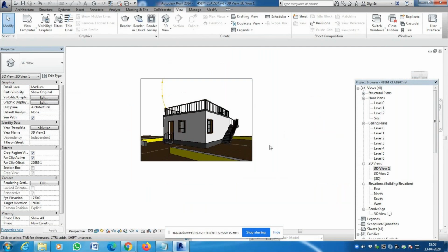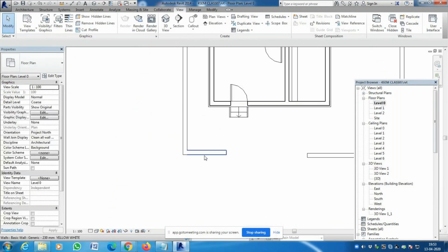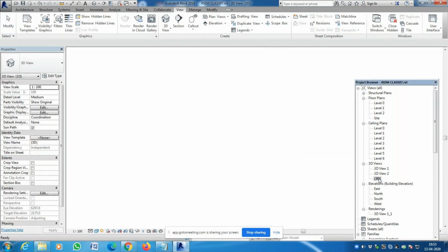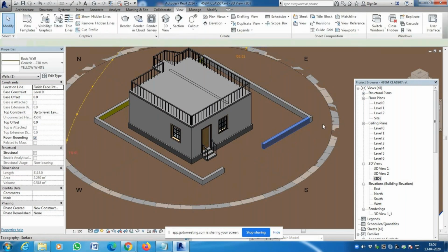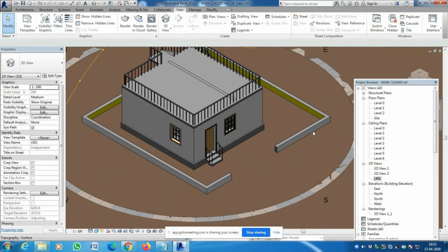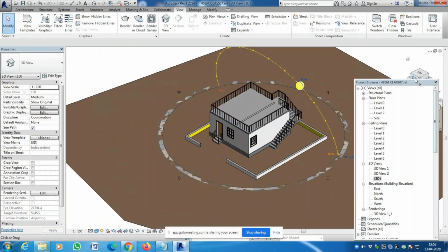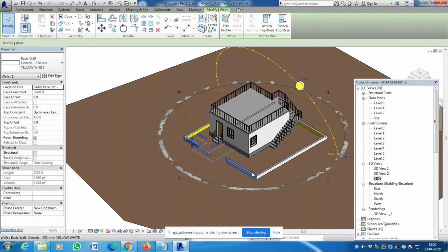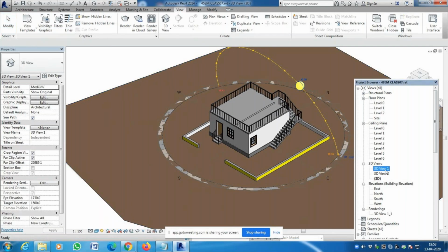So here we have some problems. That is while constructing, I think I made this in a different way. So I can do one thing. If you go to 3D, this is very helpful to sort out things like this. And select this, give a space bar. So exterior side will always become okay. Give a space bar. Exterior is always white and interior is going to be yellow. Oh, sorry, we need exterior yellow. I'm sorry. So I'm just going to flip all these walls by just clicking on the space bar. So I got what I wanted.